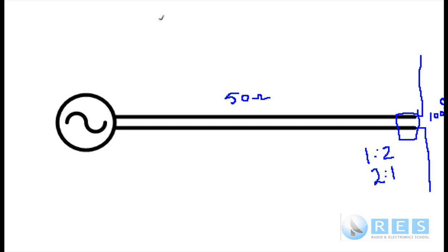There's a really big fallacy out there that baluns are transformers. You're used to a transformer having a primary and a secondary and a laminated core or a ferrite core. You can make a balun using a mutually coupled transformer. But if we did that, these types of baluns are very narrow bandwidth, and radio amateurs operate over a wide band of frequencies. So we don't use mutually coupled inductors or transformers to make our baluns. We use a different principle.